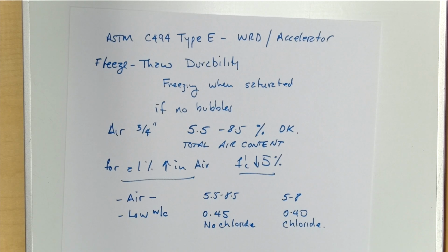One, it'll pull the air out. Two, you may form a film of little air bubbles that are compressed and elongated down about 3 millimeters, and then the surface just peels off. Also a bad day, right? Because it generally happens as someone is starting to put in the cabinets in the floor and they go like, hey, how come the floor falls apart?